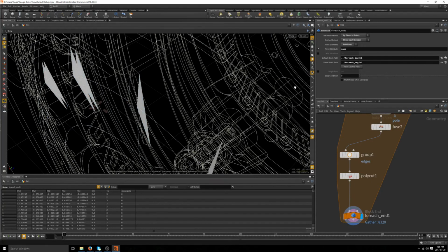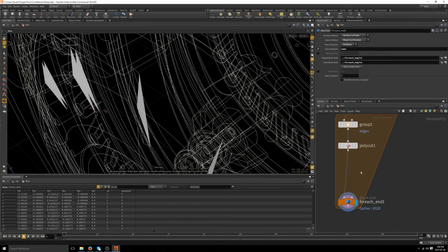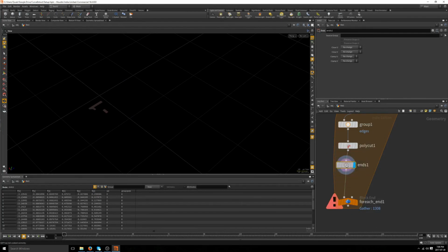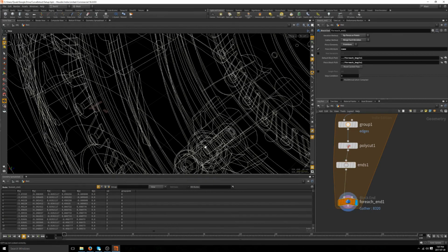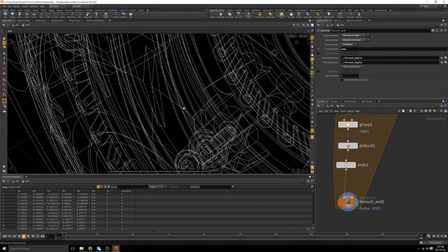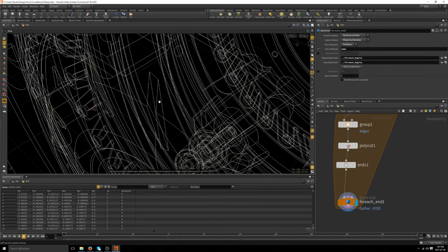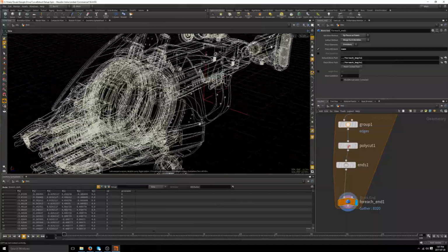So to remove these last polygons, we can use an AND operator, and we're gonna process them. We're gonna just choose unwelded on a closed U, and that's one way to remove all the polygons and keep the lines. Or you can also use a carve operator for that, doesn't matter. So voilà, the small triangles we have here are deleted.